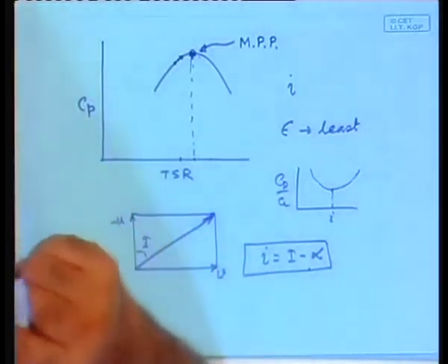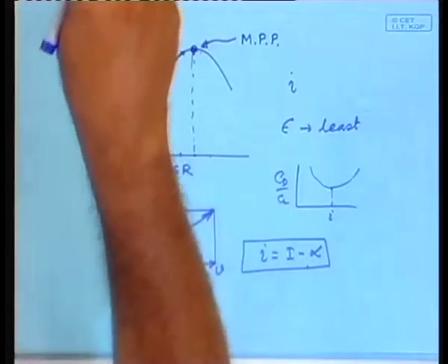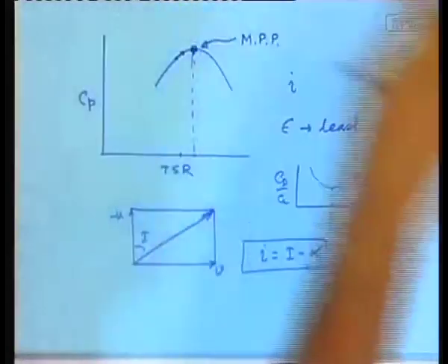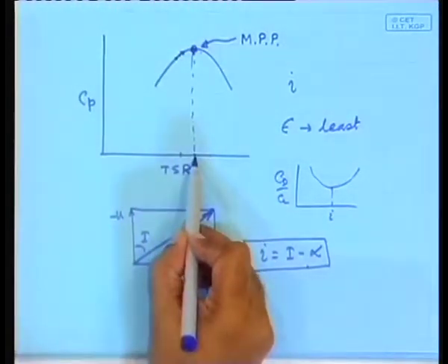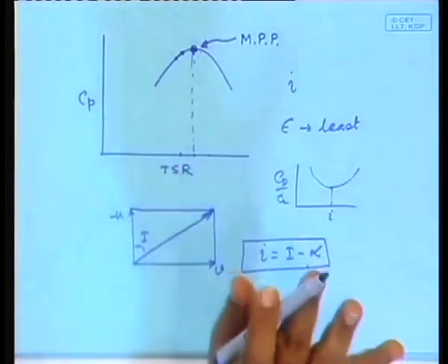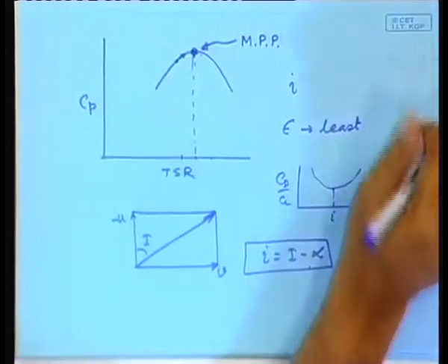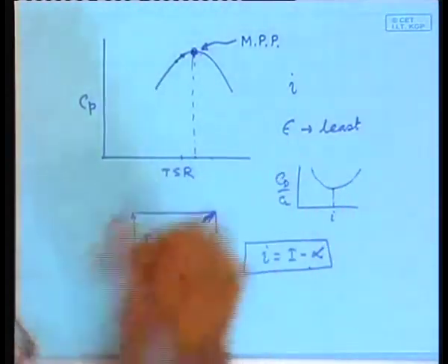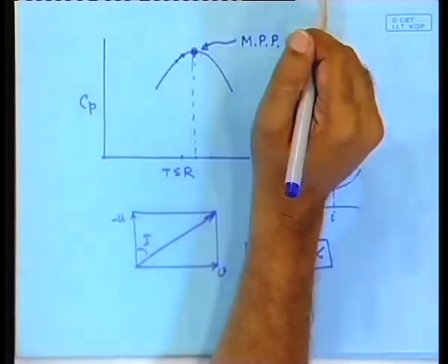What was the logic I said? The logic is that you store in a microprocessor, the controller is driven by a microprocessor, the value of the tip speed ratio. And depending on that you do your control, fine. Logically it is simple, but the practical difficulty is, firstly, how do you find out this for a big wind turbine? It is not easy.